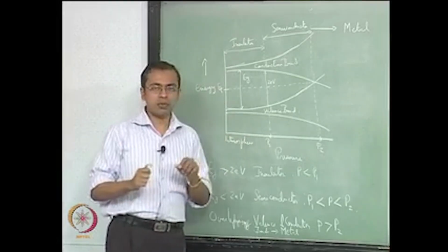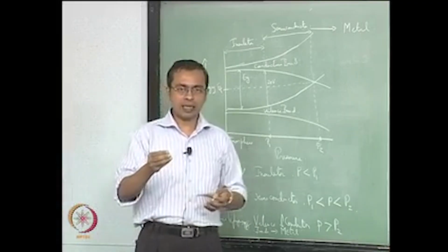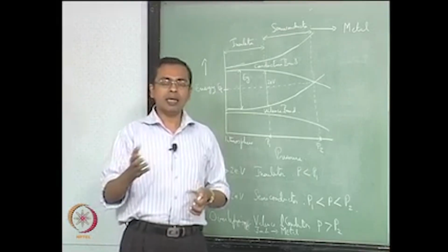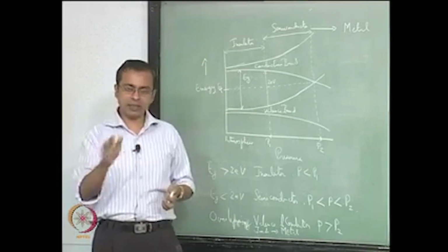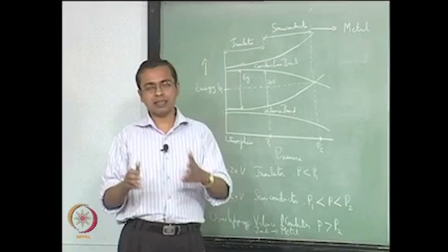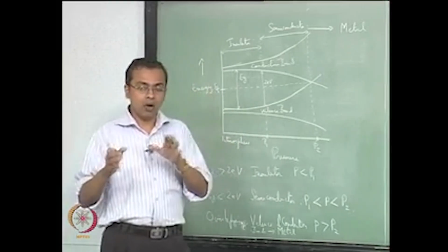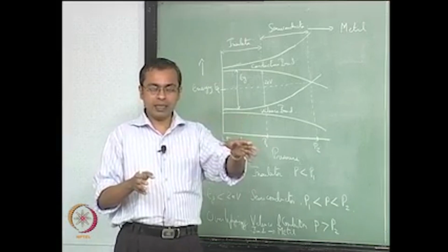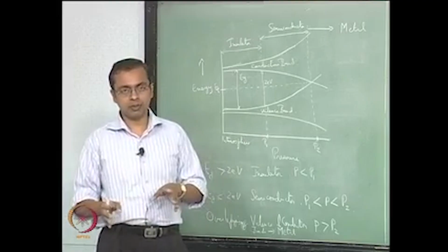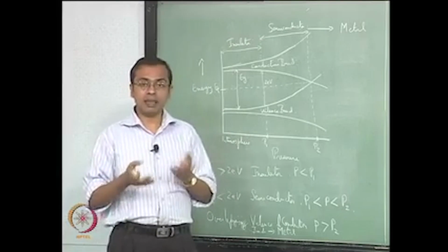It means first of all that when we test materials, we have to always keep in mind that often we are testing materials at room temperature and atmospheric pressure. We can always test them under special conditions, there is no doubt about it, but sometimes we forget that we are conducting a test at room temperature and atmospheric pressure, we are taking it for granted. Often the end use of the material may be under conditions where the temperature and pressure are very different from room temperature and atmospheric pressure. Therefore, at that point many things about that material might change.